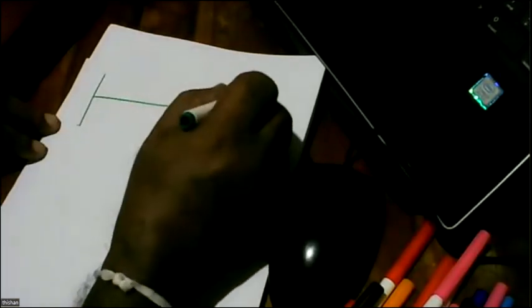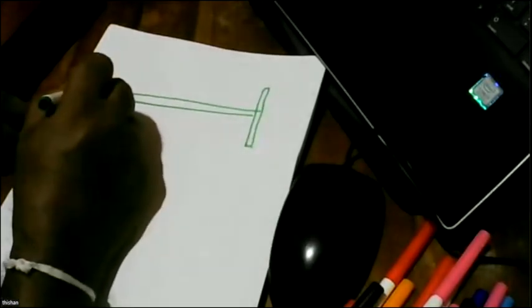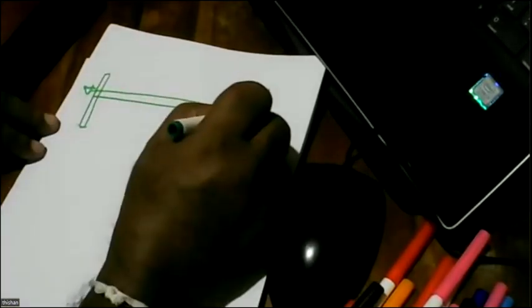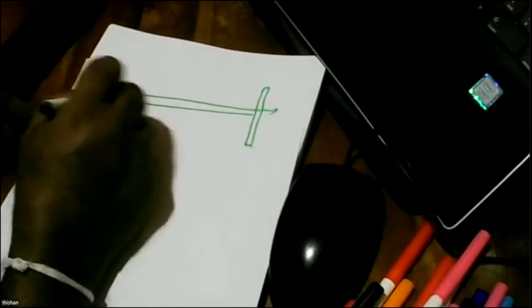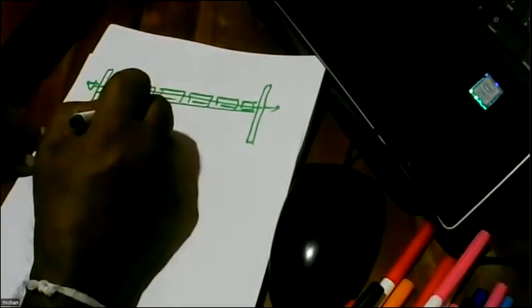We create some abutments, and these abutments have to be properly constructed. So you have to bury steel sections and create the abutments. And then we have a very long line of prestressing, stress it, and then we cast beams around it. So that is the long line method.